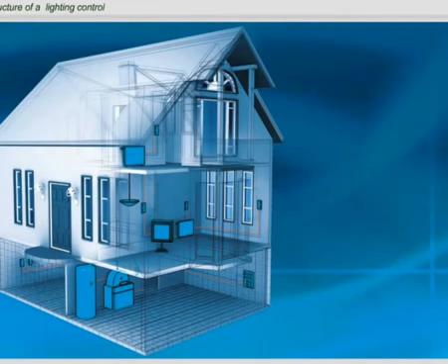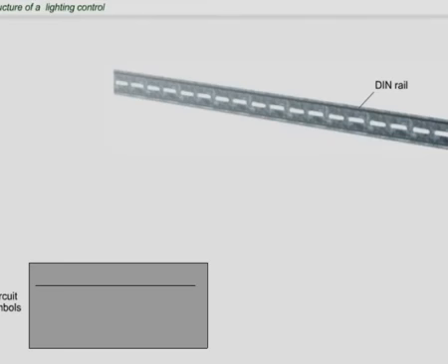In our example, the easiest task of our customer's lighting control system is to switch a single lamp on or off. Only a handful of components are required in order to implement this with EIB KNX. You can have a look at the required components now. Many EIB KNX devices are designed as modular DIN rail components. In the distribution board, they are snapped onto a DIN rail.